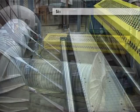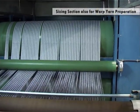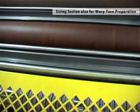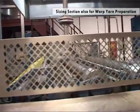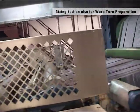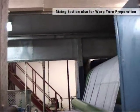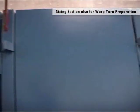Sizing is a complementary operation which is carried out on warps formed by spun yarns with insufficient tenacity or by continuous filament yarns with zero twist. In general, when sizing is necessary, the yarn is beam warped. Therefore, all beams are fed as soon as warping is completed to the sizing machine where they are assembled.